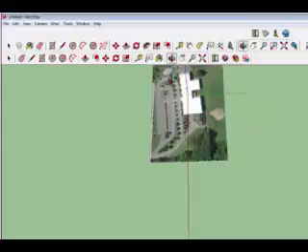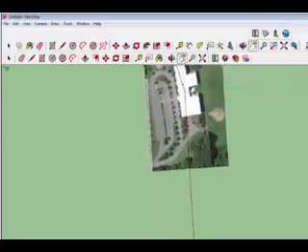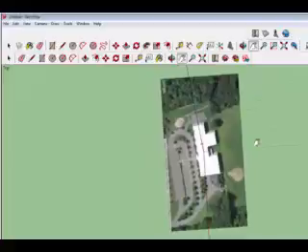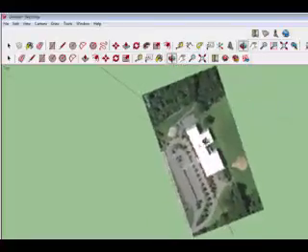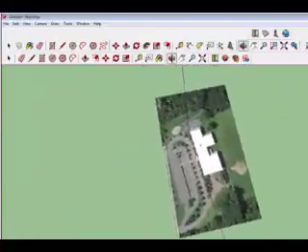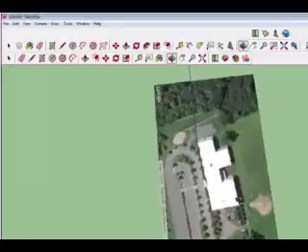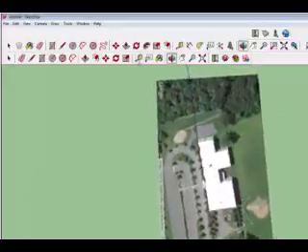So I'm using the orbit tool. I use the grab pan tool there. So now you have their actual, in this case I have the students put their house actually built in. The next step is you take the axes, you pick a corner, pick another corner, and I'm clicking, and then up here I'm going to click, and it will make the X, Y, and Z axis now line up to it. So when you orbit, it's on the actual building. I'll zoom in a little bit, and that will give you the ability to now build right onto it.